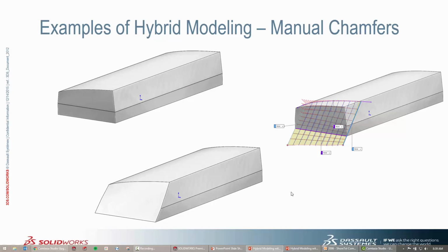All right, so that was a manual chamfer, and again, the technique that I used there to create the sketch base for my boundary surface, you can use that in lots of different scenarios. And then the cut with surface, that's a really great tool where you use a surface as a supporting or reference geometry to actually allow another feature to exist, hence the cut with surface.